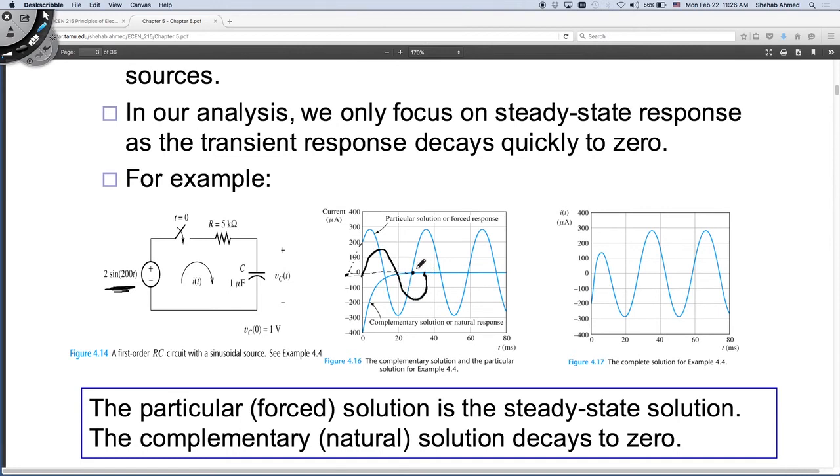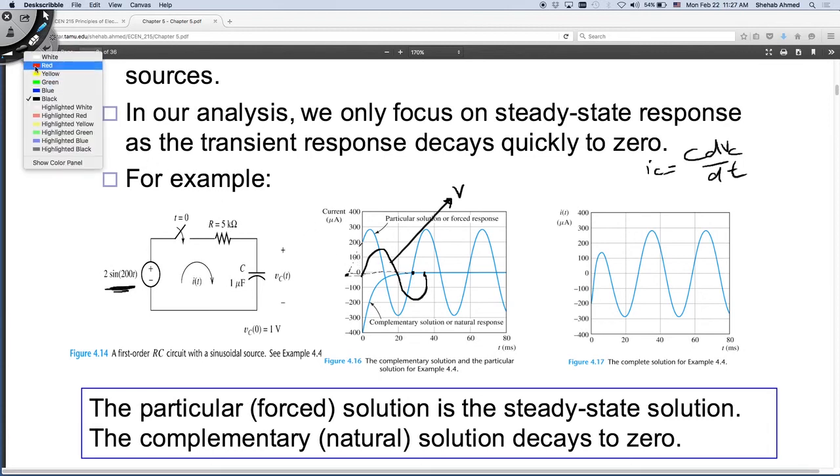This is my attempt to draw this, right? So this was the voltage that you applied. This is 200 sine t. If it was a pure capacitive circuit, IC, the current that I'm drawing, equals C dV by dt, where V is the voltage across the capacitor. Some of the voltage is across the capacitor, some across the resistor, but for simplicity, let's assume it's all across the capacitor. Then IC is the differentiation of that, and differentiation of a sine is a cosine. So you'd expect the current to lead by 90 degrees, and the current would look like this.